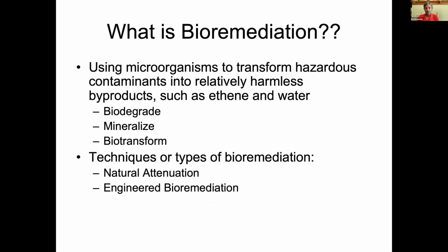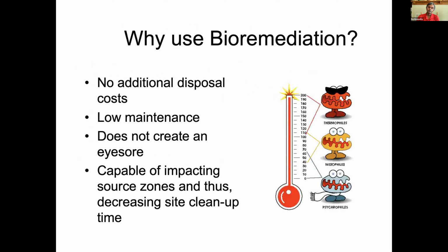So the techniques involved in bioremediation are broadly classified as natural attenuation and engineered bioremediation. Natural attenuation is basically monitoring. Almost everything is available to the microorganisms, and conditions are right, so you simply monitor the concentration in the environment. So it's mostly a passive bioremediation. Engineered bioremediation is where we alter the conditions to keep the optimum condition for microbes to degrade the chemicals.